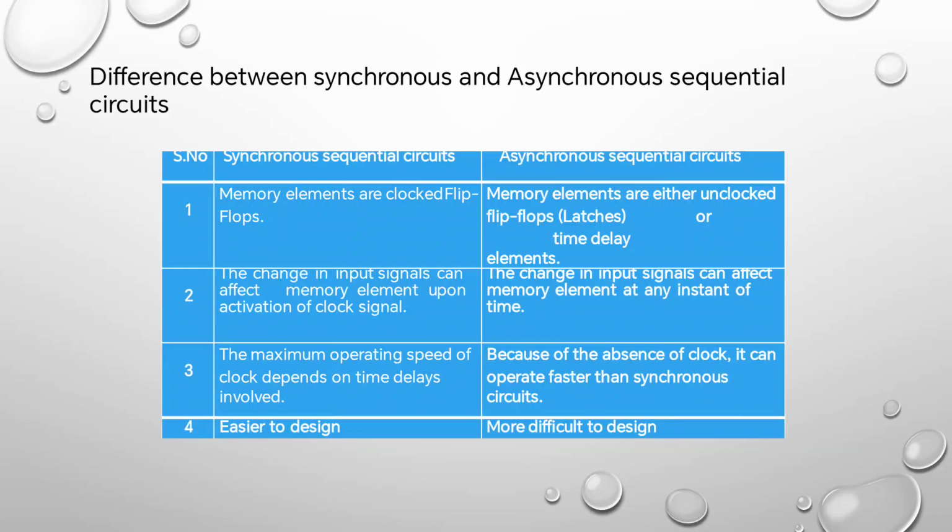The maximum operating speed of the clock depends on the time delays involved in synchronous circuits. And because of the absence of clock, asynchronous sequential circuits can operate faster than synchronous circuits. Synchronous circuits are easy to design, but asynchronous circuits are more difficult to design.